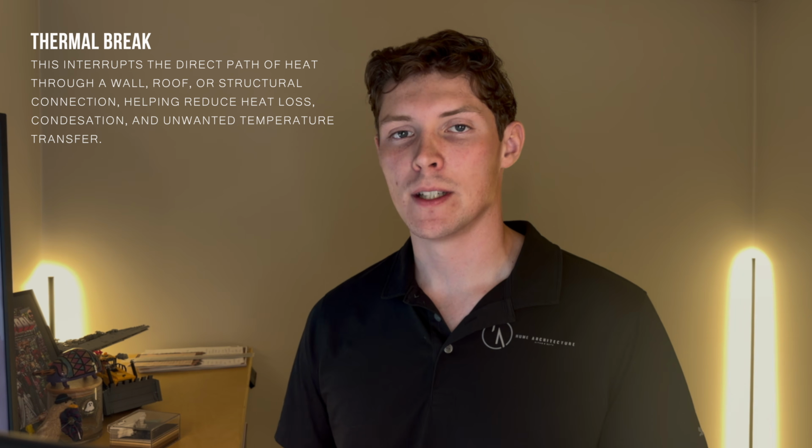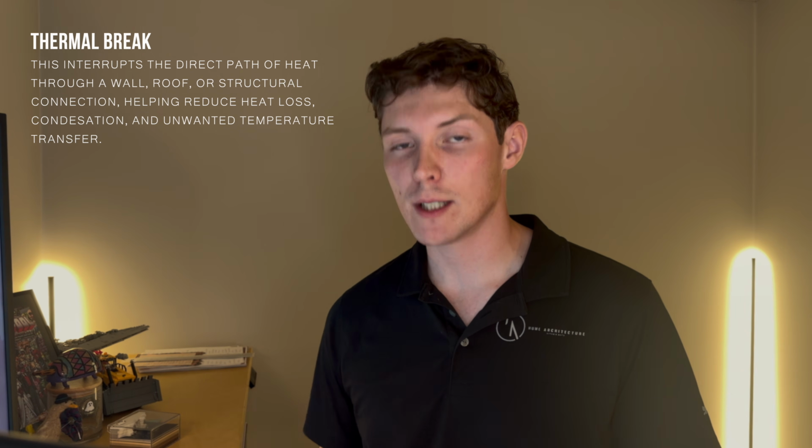So maybe you're gonna bump up insulation in the foundation, in the roof, or you can do continuous insulation, which is a foam board that you put on the exterior, or you can do any other form of water resistant material that allows for a thermal break between the exterior and the interior. All of these details are extremely important as we come into the design of the home.